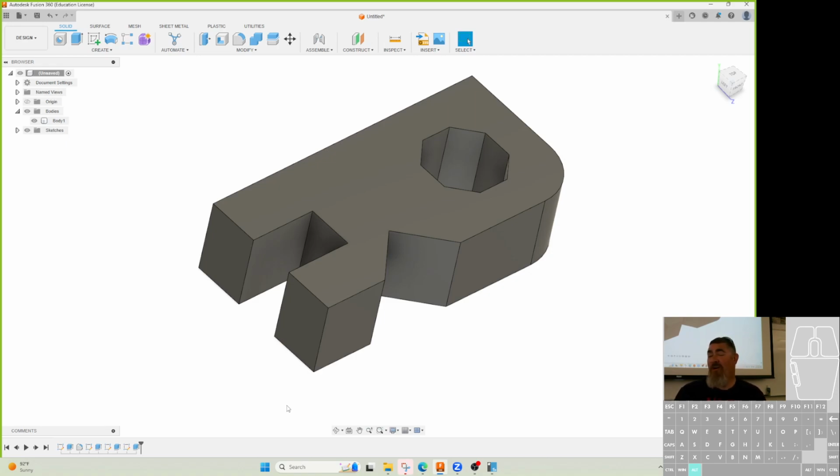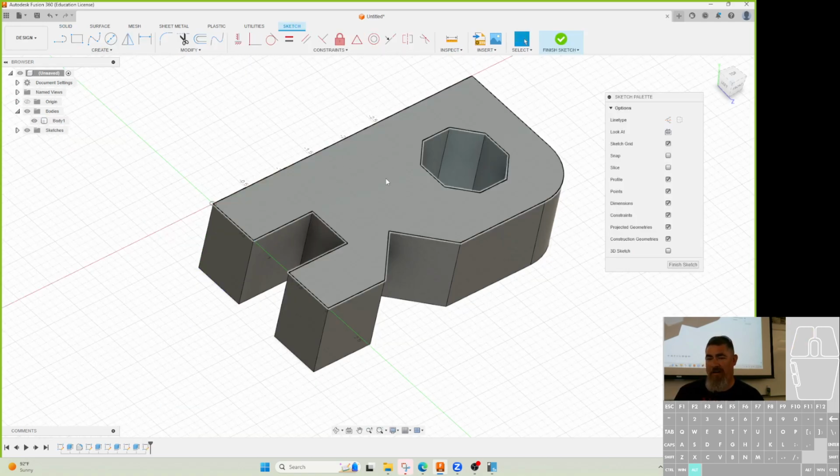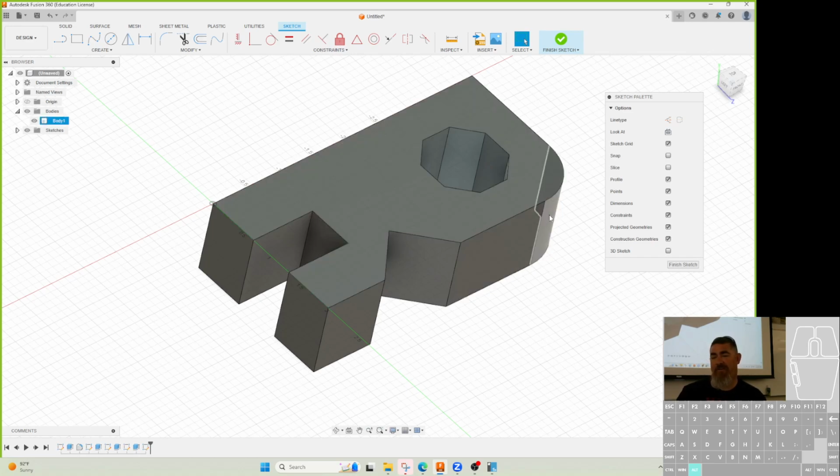What's the question again? When would I actually need to make the radius on the sketch? So if I'm going to create the sketch and I need to do something and I need to have the radius show up on the sketch, instead of being able to draw a square or a triangle with a sharp point, when would I actually need to have that radius show up in the sketch? When you're doing an arc? When they're not the same. Because here I needed an arc, but I was able to draw a square and add the fillet. Oh, okay. Same thing here, same thing when I did it here.